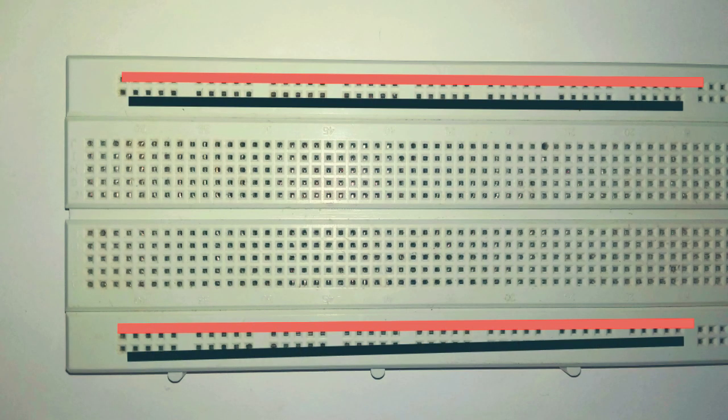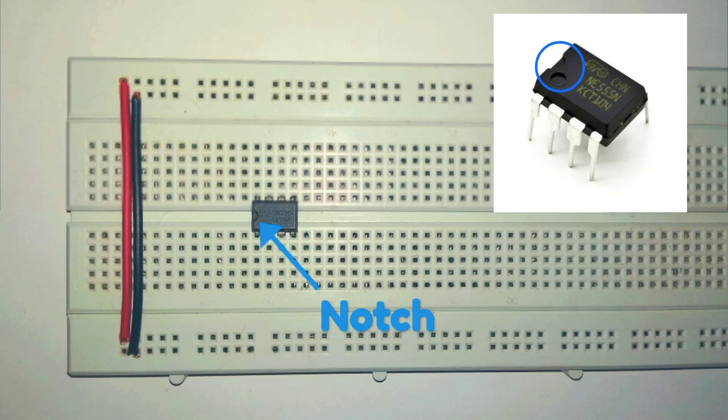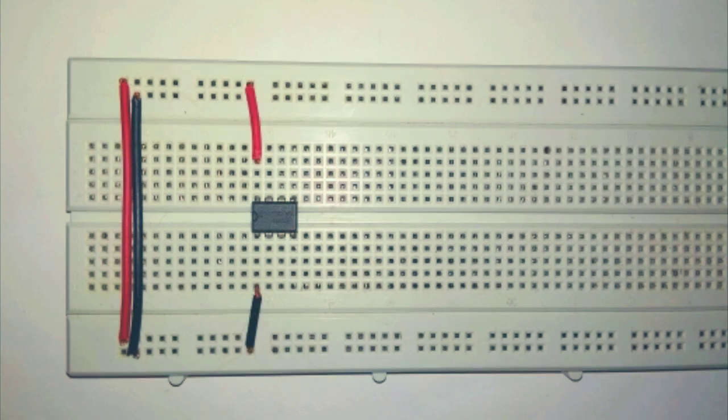I will use these rows as power lines for our circuit, so let's first connect them together. Now connect 555 IC on a breadboard, but make sure that the notch of the IC faces the correct direction. Now connect pin 1 of IC to negative rail and pin 8 to positive rail. These pins are used to power the IC. Now connect pin 4 of IC to positive rail of breadboard. We need to tie this pin high because it is an active low pin. It can accidentally reset the IC if left floating.